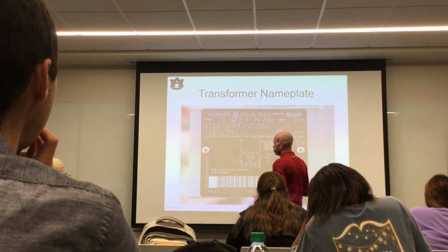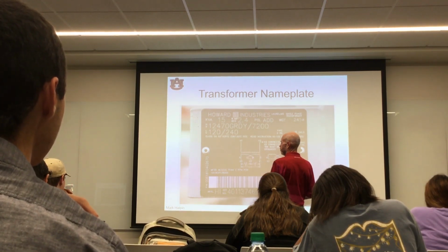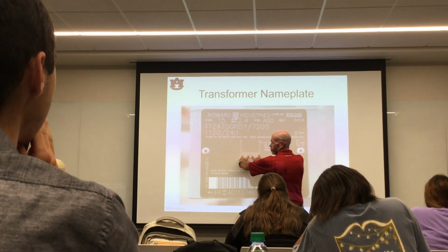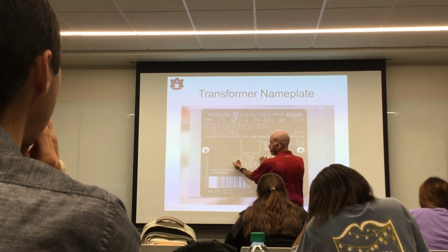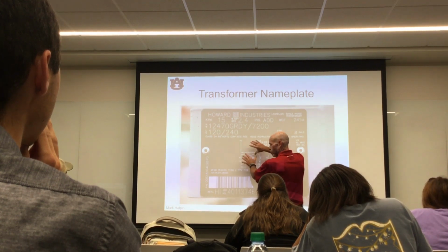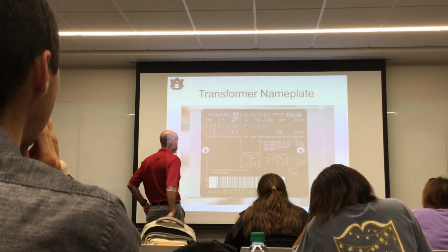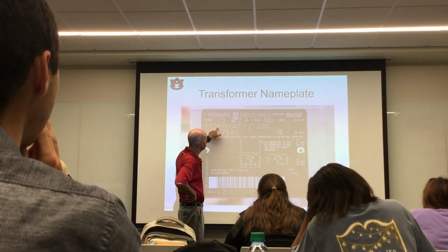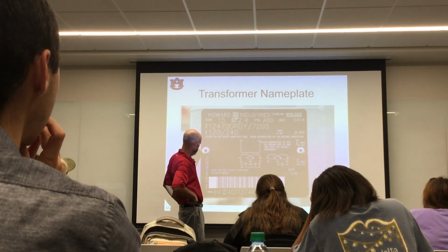I also told you that a transformer like that serves your house, it has 1 high voltage winding, it has 2 low voltage windings. Each of these would be 120 volts, and so when you tie them together like that, then here you got 240. Okay, so this is what we were talking about in some of those other pictures. So what all else we got up here? Well, here's the power rating, okay? Here's the voltage information.